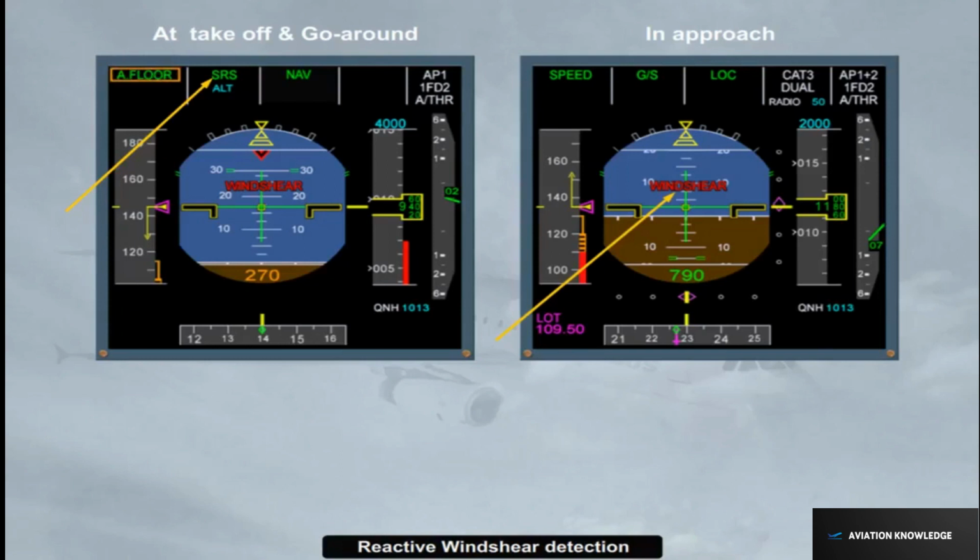Note, if the angle of attack gets too high and reaches the fly-by-wire angle of attack protection, the autopilot disengages. The fly-by-wire maximum angle of attack protection assists the pilot to best react.